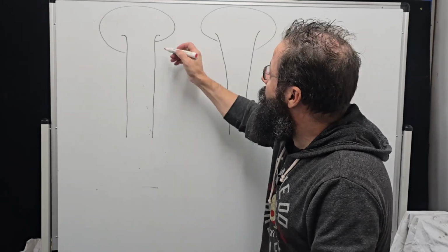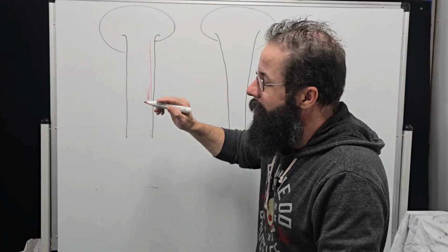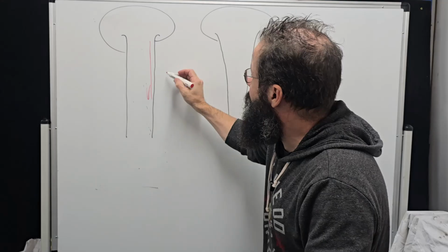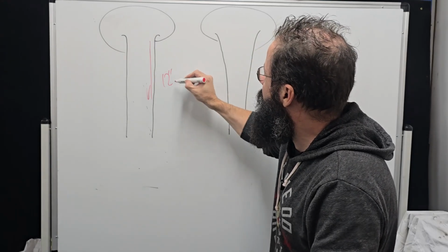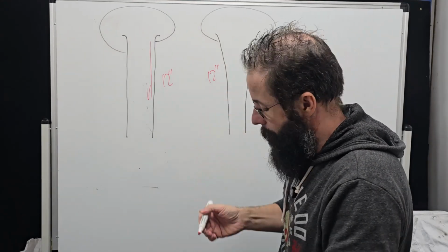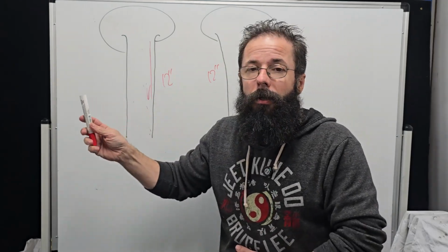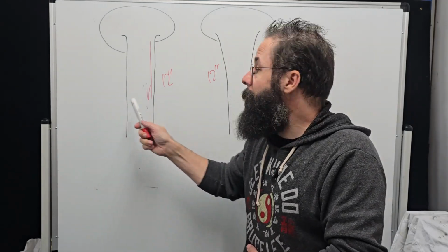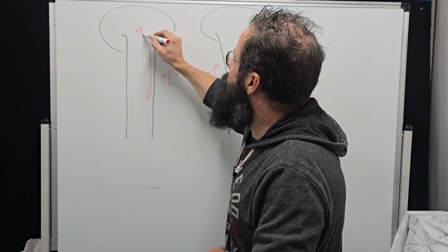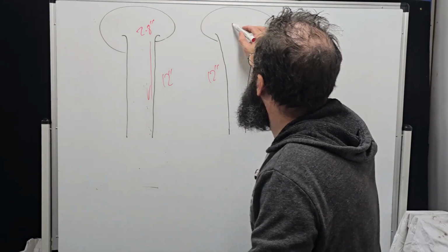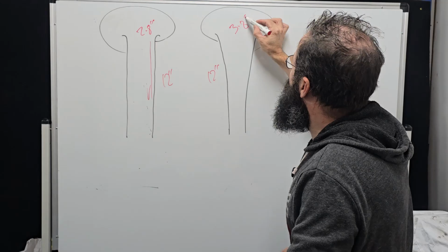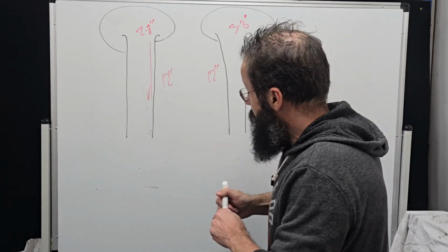The first being obviously time over distance. This is going to have a hell of a lot more restrictions. So let's say this is 12 inches off the head and this is 12 inches off the head. This runner is going to choke 1,000 RPM earlier. So let's say this is 2.8 and this is say 3.8. We've got a little bit of taper in this one.